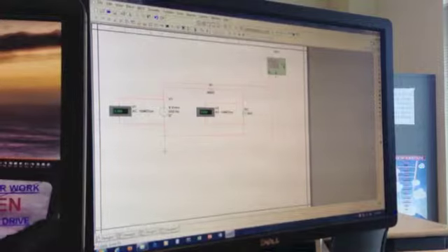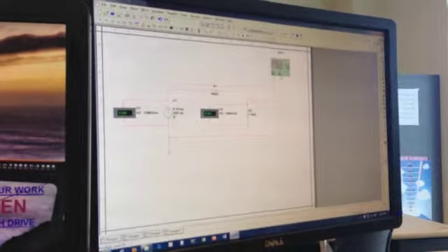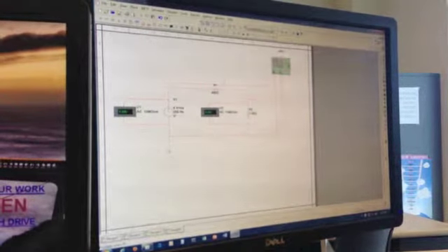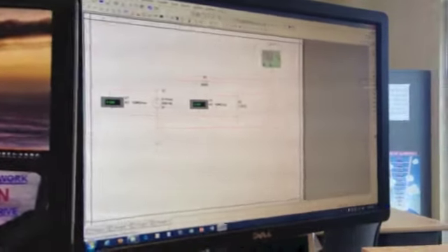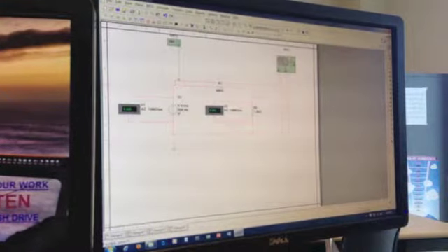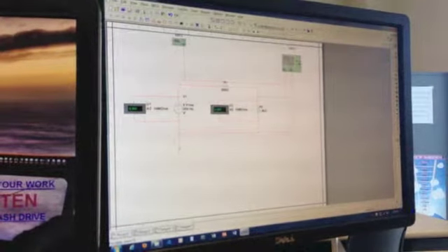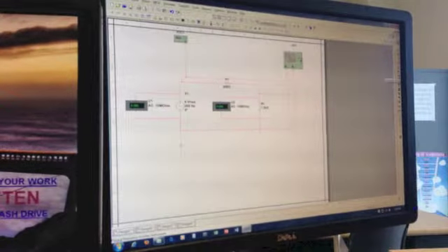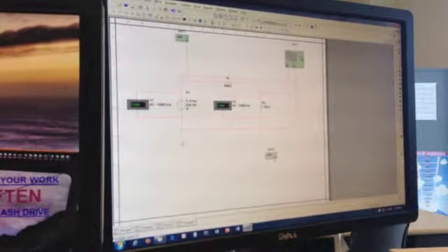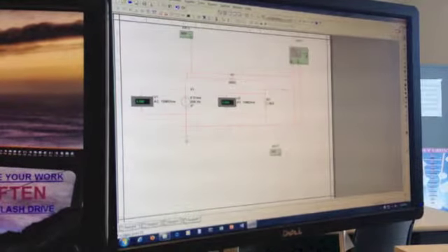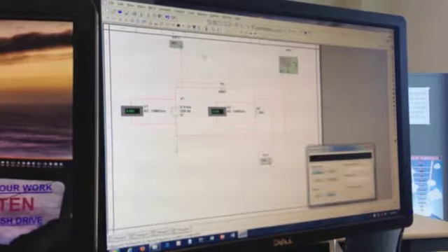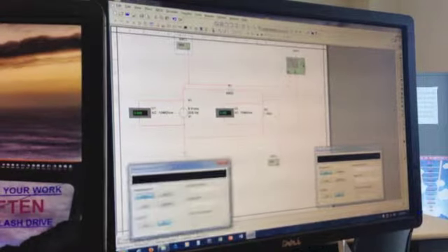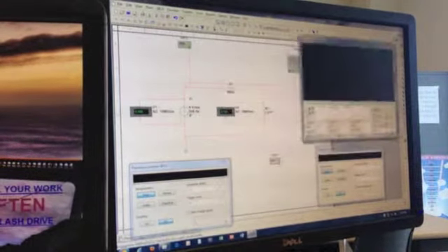For B, we'll connect that to R2 and then to the ground as well. Then we'll add a frequency counter to the positive lead of the oscilloscope for channel A, and another to the positive lead for channel B, which is going to measure the R2 resistor. We'll double click them so we can see the values, and the oscilloscope as well.